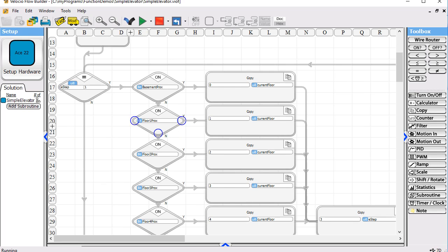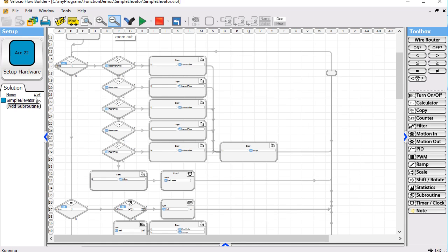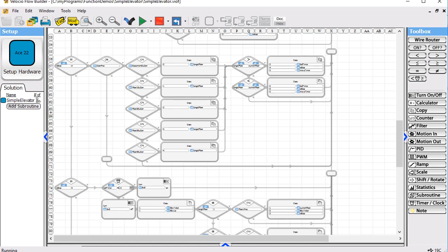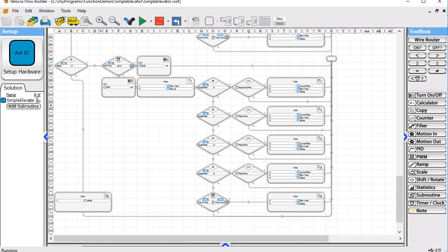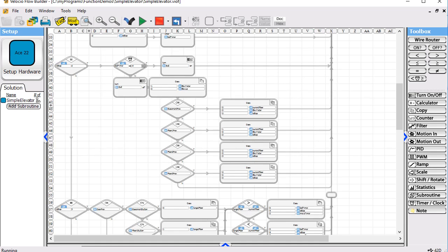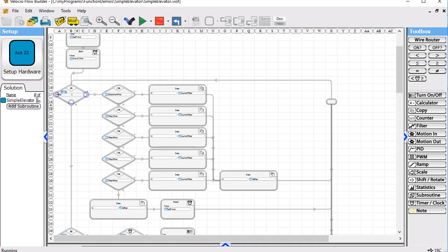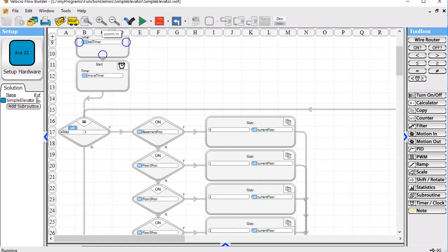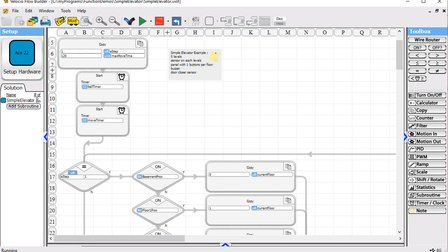And then after we do that, we go into our loop. If you take a look at the program overall, this is just one big loop. We go through, we do something, and we come back around, we check the next thing. And within this loop, we've got 5 steps or 5 states in our state machine. We initialize our state machine to step 1. So the very first thing that we do is come down and we see that we are at step 1.